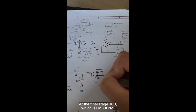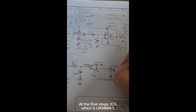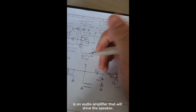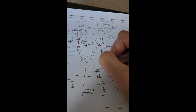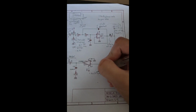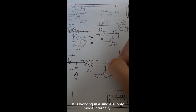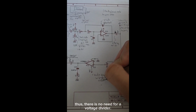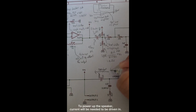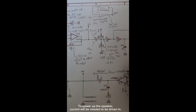At the final stage, IC3, which is LM386N-1, is an audio amplifier that will drive a speaker. It is working in a single supply mode internally. Thus, there is no need for a voltage divider. To power up the speaker, current will be needed to be driven in.